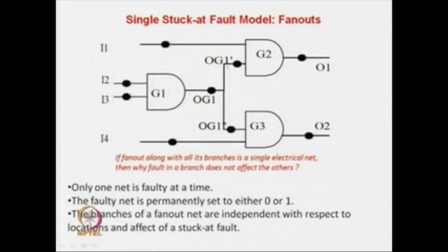So, now in this case, if you are doing structural testing, not at the functional level but at the fault model level, then what do we have to verify? We do not have to think that this is an AND gate and so forth. We have to just verify that this line does not have a stuck at 0 or stuck at 1, this line does not have a stuck at 0 or stuck at 1, and so forth.